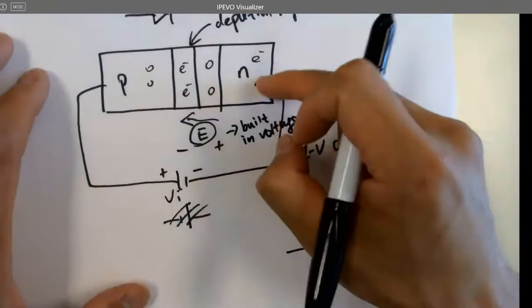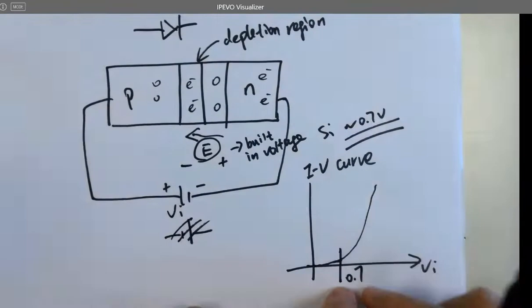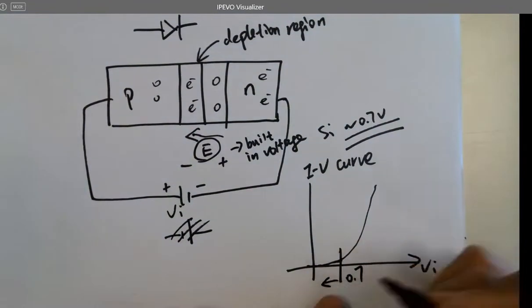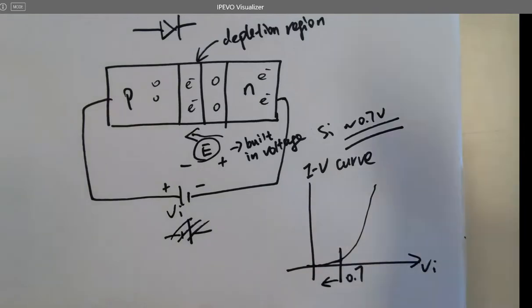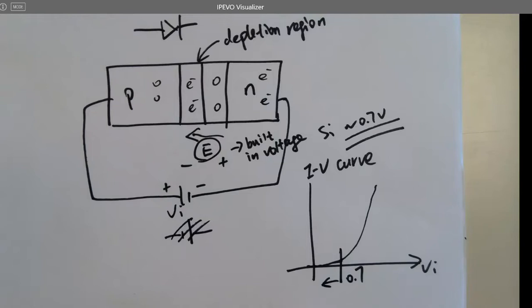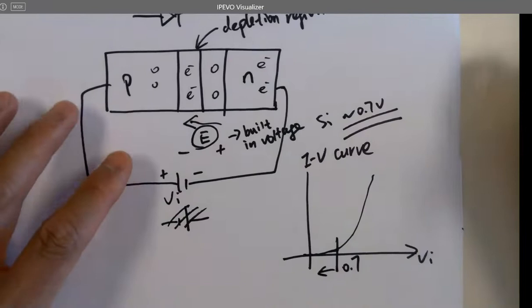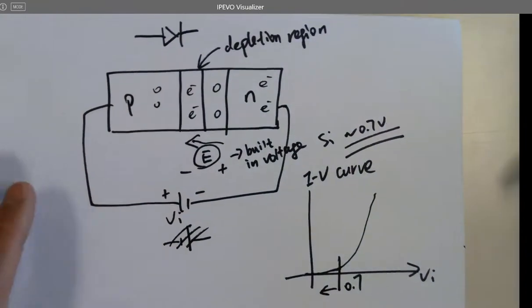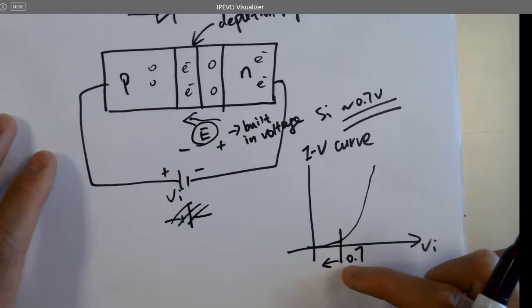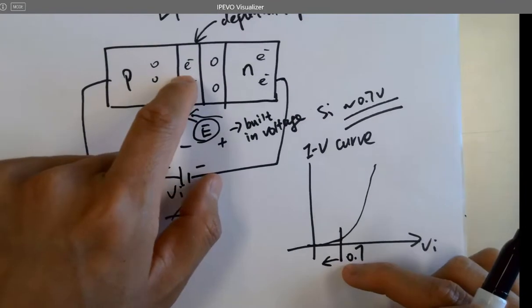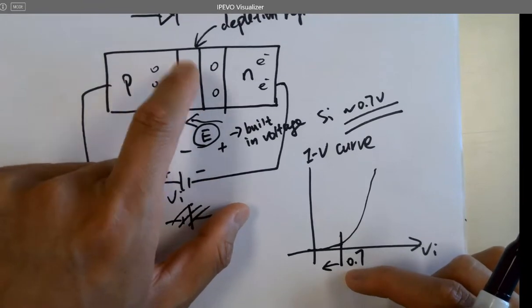Even though this is not being used for the digital circuits, it's the foundation of it. It forms the threshold voltage. Whenever the voltage is lower than that, it's considered logic low. Whenever it overcomes that threshold voltage, it turns on the transistor and becomes logic high, right? So we got 0s and 1s for digital circuits. And that's partially why it's called a semiconductor, because it's not really conductive. You have to overcome that threshold voltage in order to make it conductive. That forms all these modern electronics in your phone, laptop. That's the foundation of everything, pretty much.